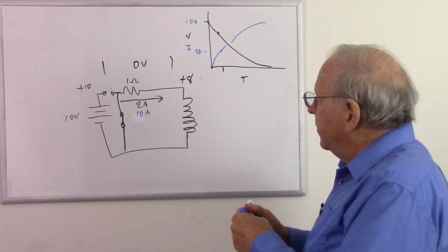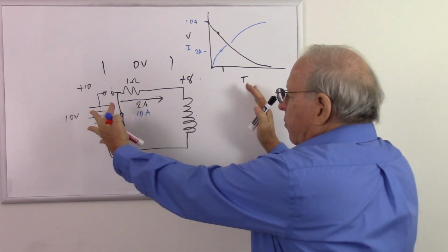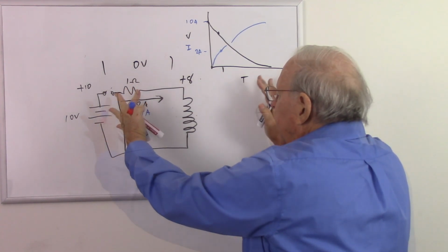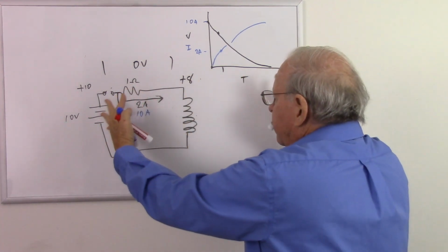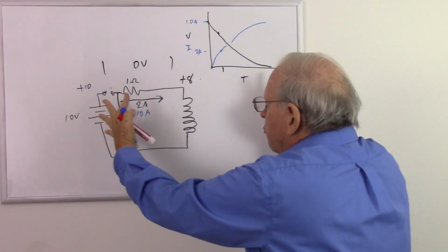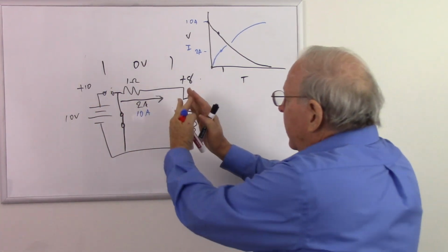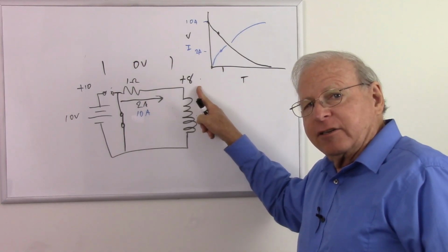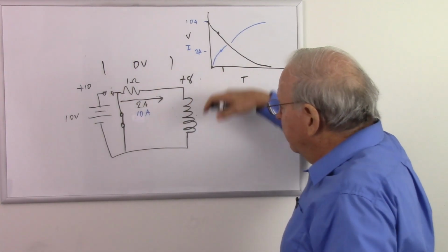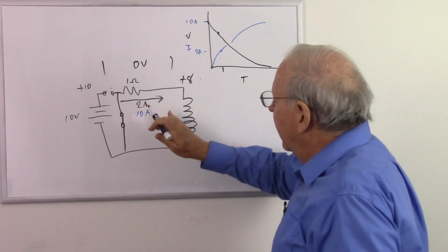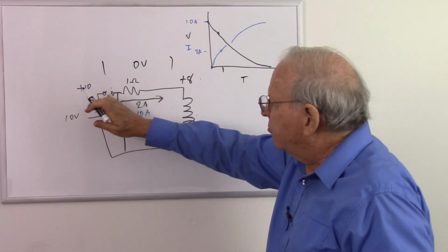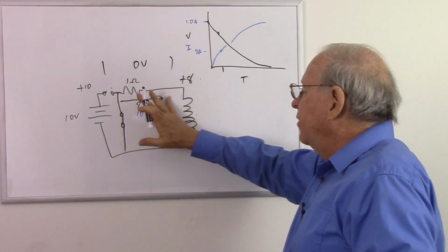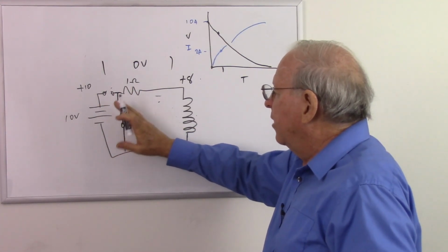So what's going to happen? Now I have all this energy stored in this coil. And since I'm no longer pushing current into it, there's nothing to keep that magnetic field sustained. So it's going to start to collapse. So now it was building and causing a force pushing this direction, but now that it's collapsing, it's going to reverse direction of its force. And that current wants to now stop because I've opened the switch. So I've opened the switch. There's nothing to push current through there anymore, so the current tries to stop.